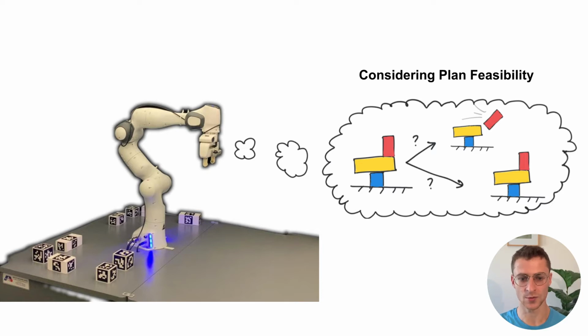Determining the feasibility of an abstract plan with the use of a simple model, such as a physics simulator, would not accurately capture the complexity of the tower building problem. This process is subject to noise in execution and estimation. Thus, we take a learning approach. The robot is given all object properties, as well as the ability to localize, pick, and place blocks. What it must learn is how to accurately predict whether or not an abstract plan is feasible.